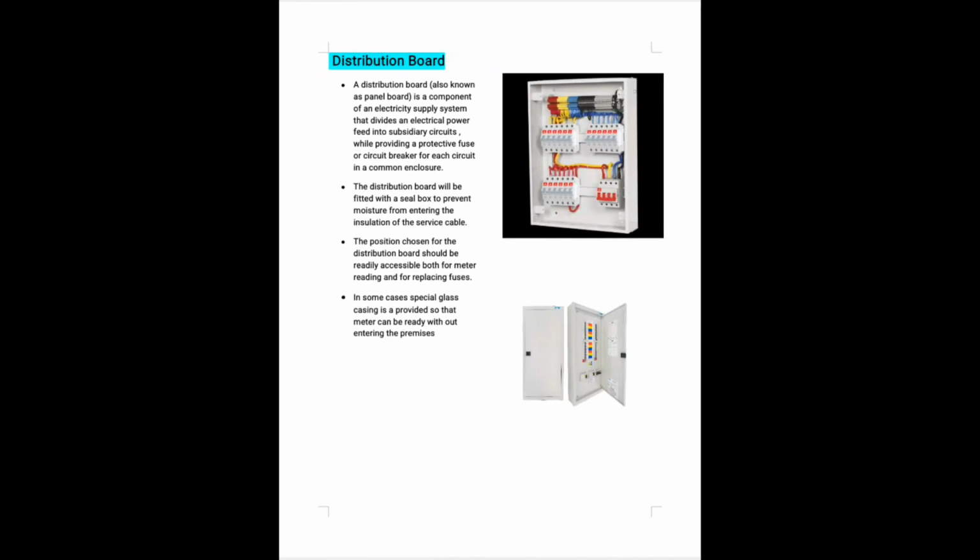Distribution board. A distribution board, also known as a panel board, is a component of an electricity supply system that divides an electrical power feed into subsidiary circuits while providing a protective fuse or circuit breaker for each circuit in a common enclosure.